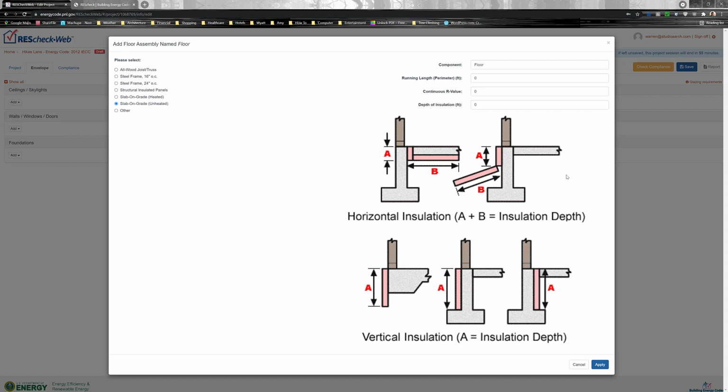specifically the insulation. Up north here, kind of, let's talk Tennessee. I'm on the eastern seaboard here, so you kind of have to make your own judgments, but sort of Tennessee and north for me. To be able to pass without going crazy on your walls, your windows, your roof, you will need foundation insulation. The energy code is pretty clear on this. And these diagrams are super helpful to that end.